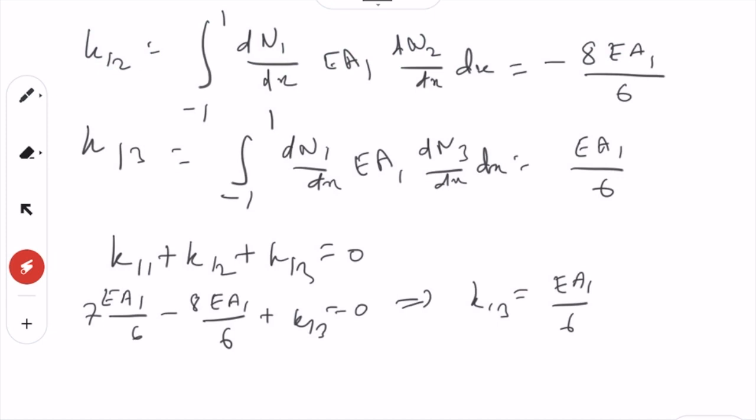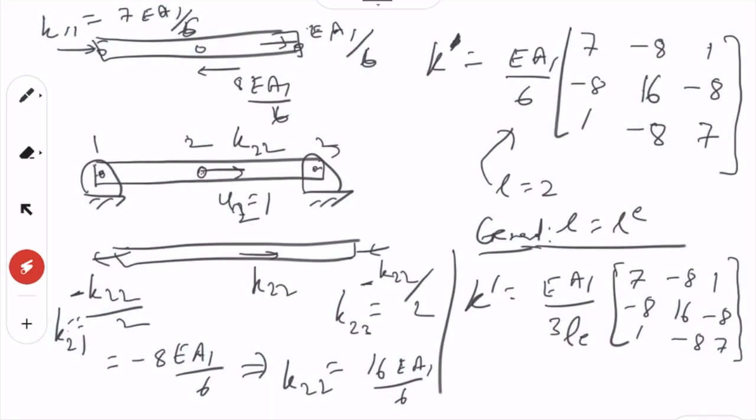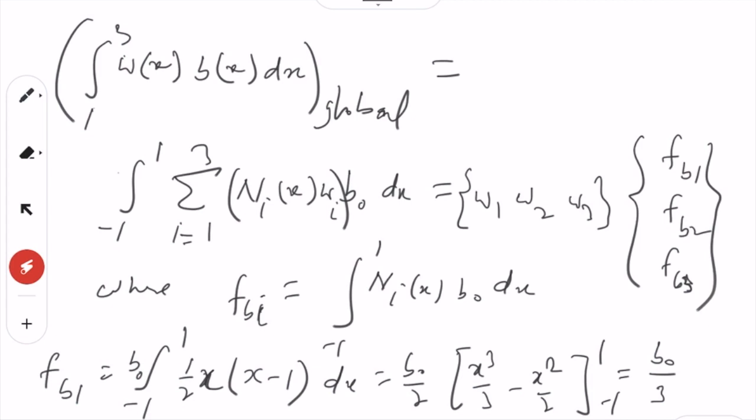We also discussed some tricks to quickly find the stiffness matrices, given that the sum of all the rows will be equal to 0 and so on. It has to be symmetric, and for one row, if you add all the entries of the stiffness matrix, it should give 0, and that way you can also get information. Based on that, you need not evaluate all the entries; you can guess or find out the logic behind that. That also I discussed, and for the 3 noded element we derived the general stiffness matrix, and we also derived the force vector.